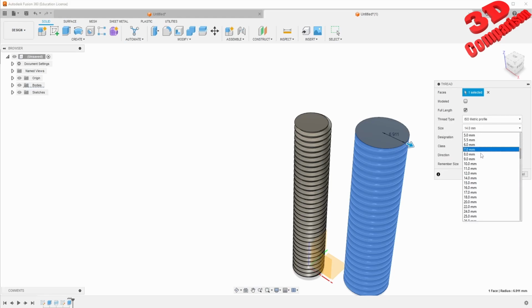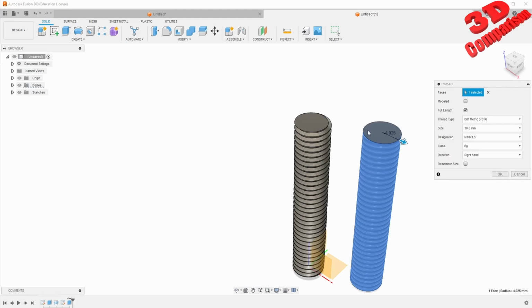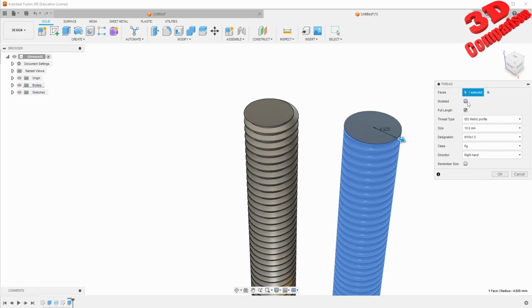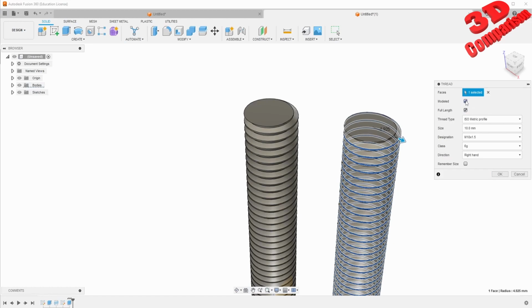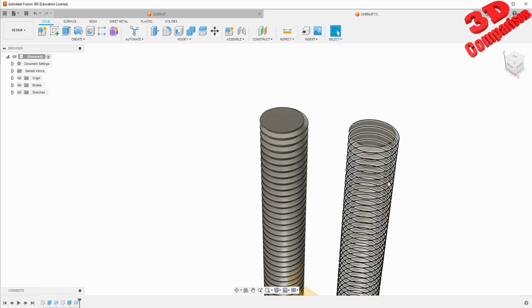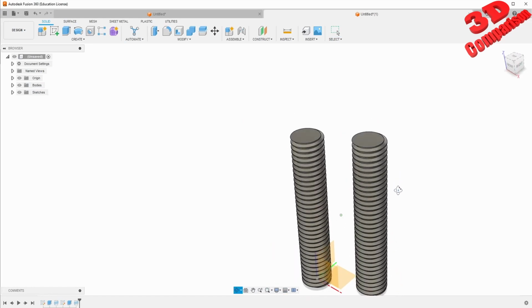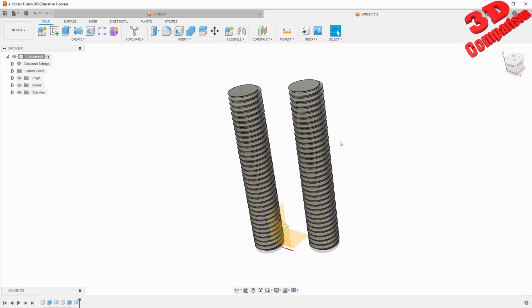But if I have this overwritten with 10, this will automatically resize the sketch. So this is really important and it saves a lot of time. And afterwards, we just click on model and we have the 3D model ready for rapid prototyping. So this is within Fusion.